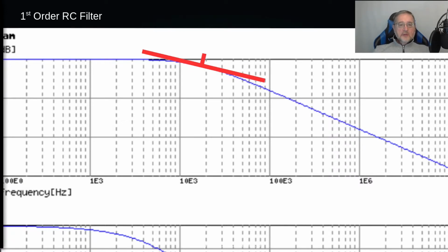In fact, it continues to increase negatively until, only far away from the cutoff frequency, it becomes constant. It is this last value that is the one that we accept as the attenuation of the filter, and you can see from the diagram that for first-order filters we need to reach a frequency of about 10 times the cutoff frequency before we reach the point where the attenuation becomes constant. For the filter in the previous episode, the cutoff frequency was around 16 kHz, and therefore the attenuation does not change anymore when we go past 160 kHz. This is the base frequency at which we should measure the attenuation of the filter, not a smaller frequency.